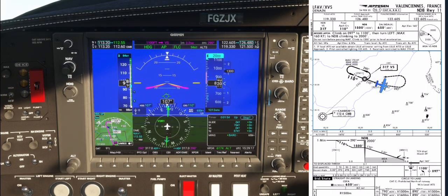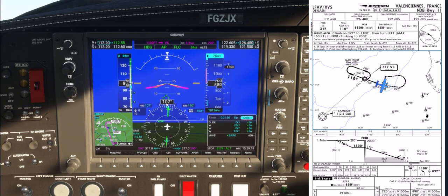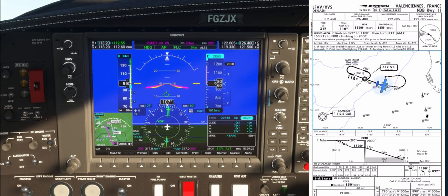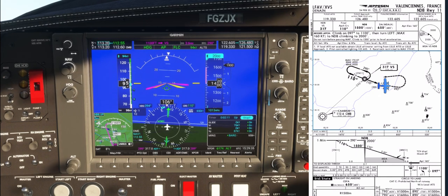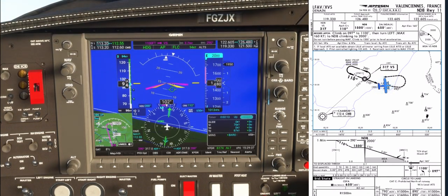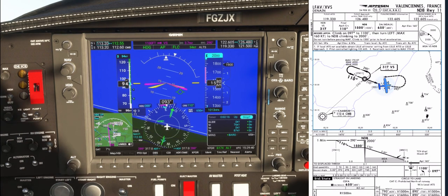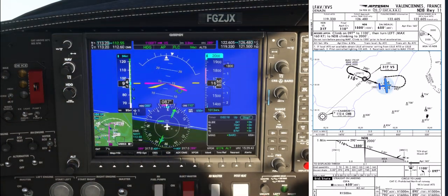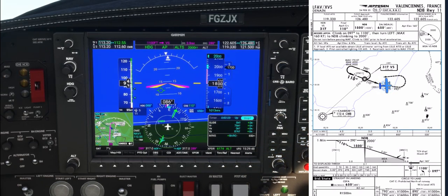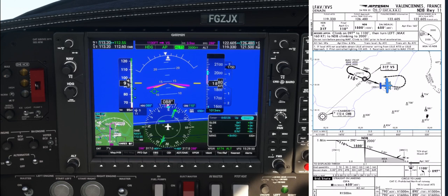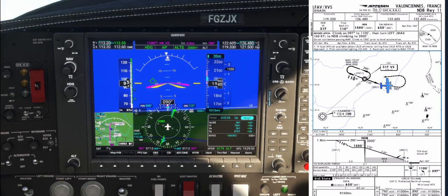You surely noticed that we arrived a bit before the end of the minute and 59 seconds. Surely because our ground speed was a bit too fast, but as we are flying this approach in CDFA, we are not allowed to fly a step waiting for the timer, so an immediate go-around is required. Fly on heading 097 degrees until passing 1,100 feet, then turn left to the NDB climbing to 2,000 feet.